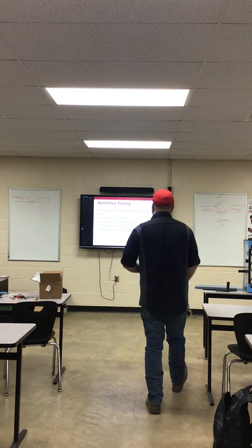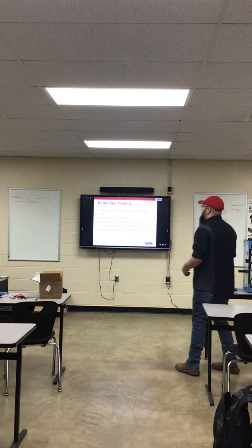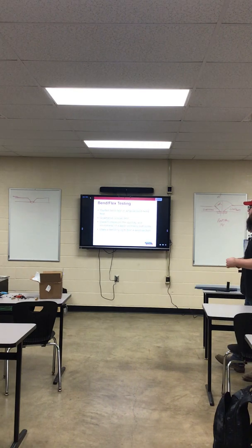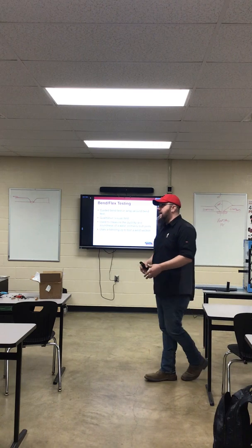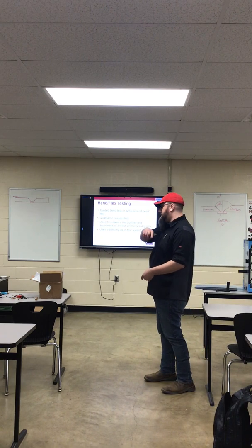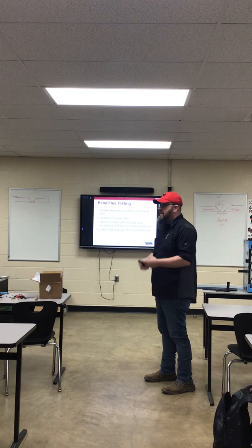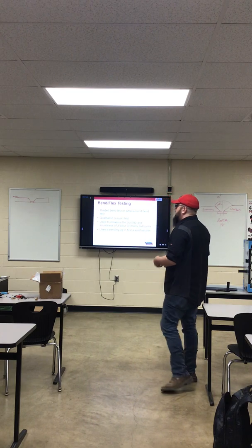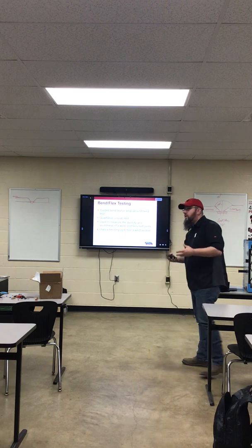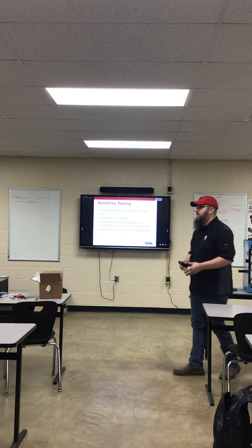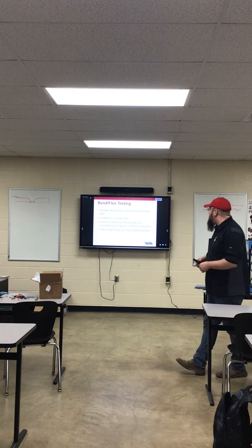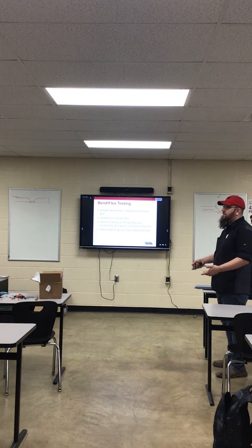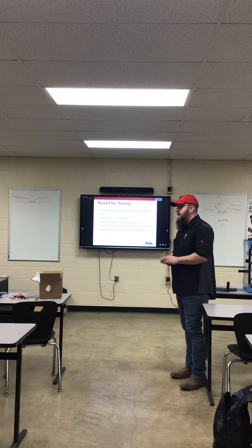Bend flex testing. We do a guided bend test for practice. It's a qualitative, it's a visual test. There's no given number that says, okay, this is 65,000 pounds of tensile strength put on that weld. All we're doing is we're stretching that weld to a known point that it should be able to operate within. It's used to measure the ductility and the soundness of a weld, primarily butt joints. Now, however, we use it for testing groove joints, right? Wrong? Right.